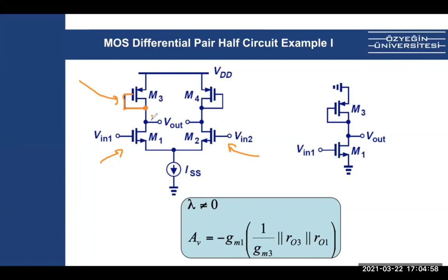So when we look at this transistor from here, what you see is 1 over GM, RO3, because you see this one, you see 1 over GM, and then there is this node, RO1. So simply, without writing the small signal, I can write the impedances at that node, right? This node, RO3, this node, RO1, and then, as I mentioned, this diode connected load, which I explained a few times in the last lecture, has the impedance 1 over GM3.